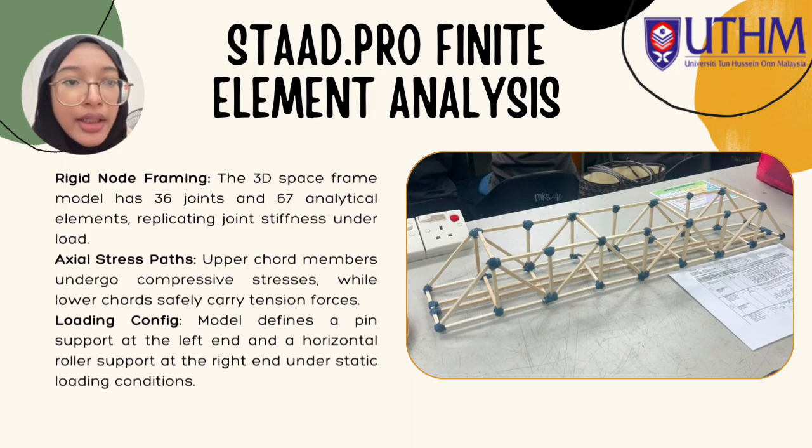Next, I will explain the finite element analysis that we carried out using StaadPro. We developed a three-dimensional space frame model consisting of 36 joints and 67 structural elements. This model accurately represents the stiffness and behavior of the truss bridge when subjected to loading. From the analysis, we observe the expected distribution of axial force. The upper chord members are mainly under compression, while the lower chord members carry tension. This confirms that our Howe truss behaves according to structural theory.